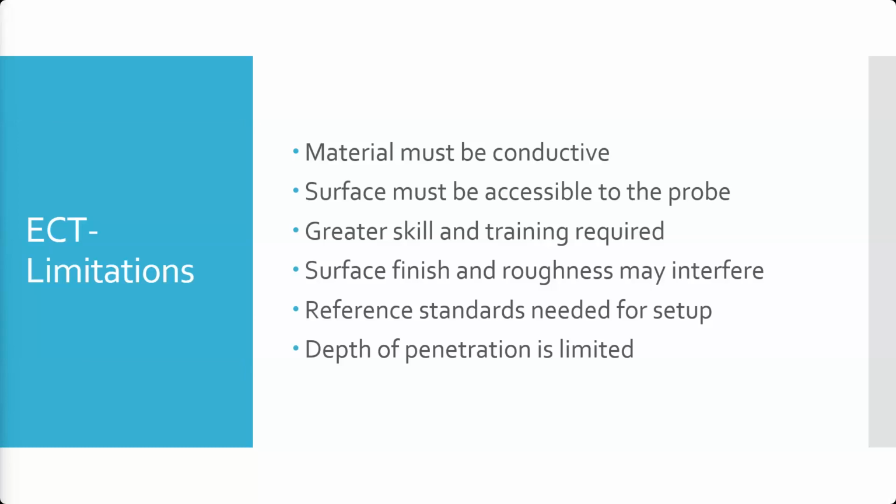It does require a certain amount of skill and training, especially for setup and for identifying a flaw or a true indication versus an irrelevant or false indication. And the surface finish or roughness can interfere with it. Because it is so sensitive, when you're moving a probe around a rough surface and it causes the probe to wobble, that will show up as a false or non-relevant indication, depending on how you want to talk about it.